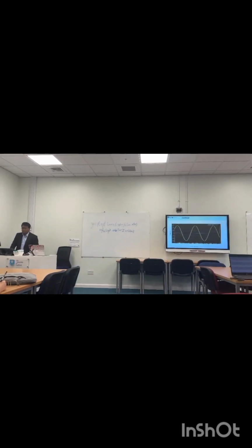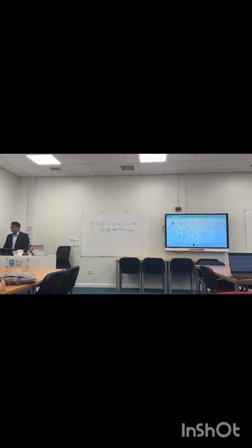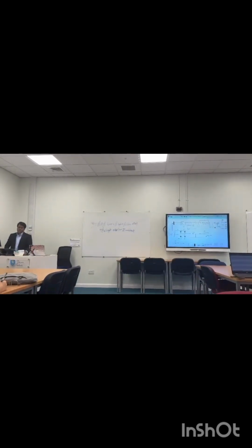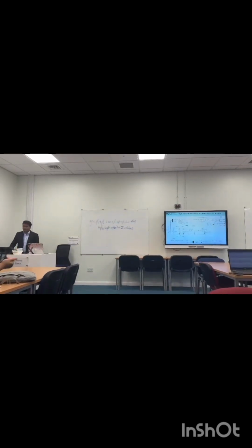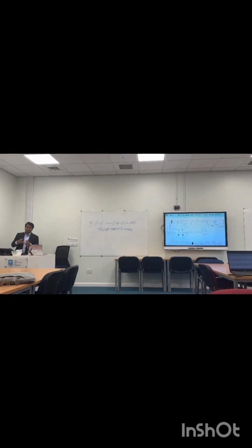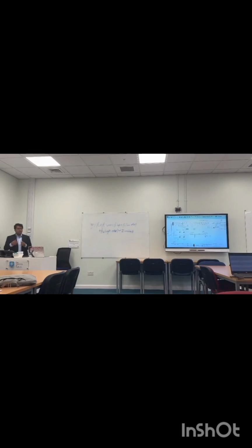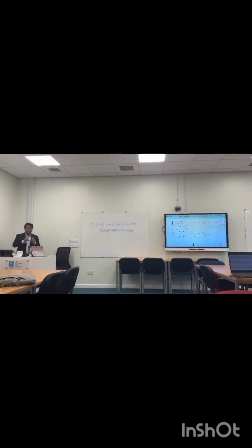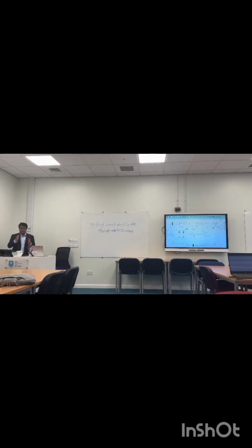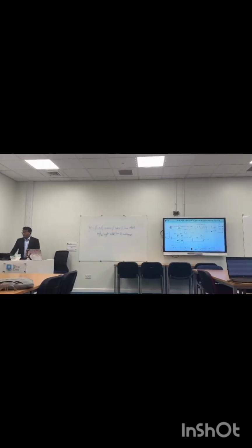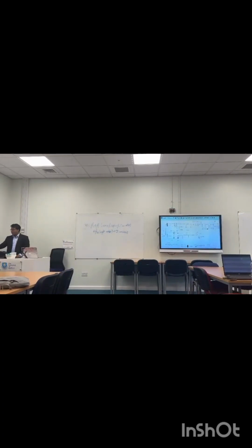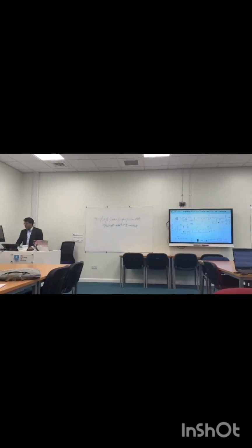And I made another simulation for single stage, single phase PV grid synchronization with a MATLAB Simulink model. There I use the MPPT, maximum power point tracking, because you know the solar panel changes with radiation from time to time. So at first I simulated it with constant radiation. Then I used radiation level change. Then there is a driver, and I get the values.